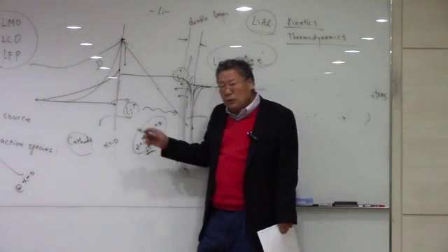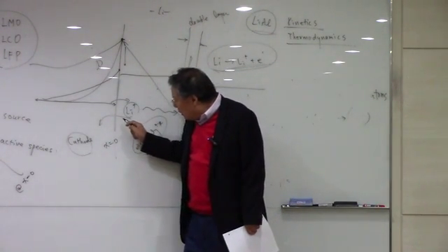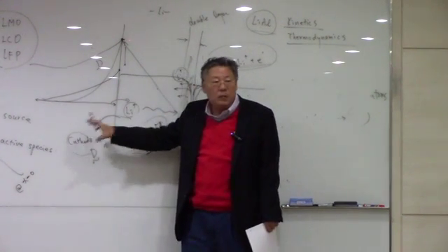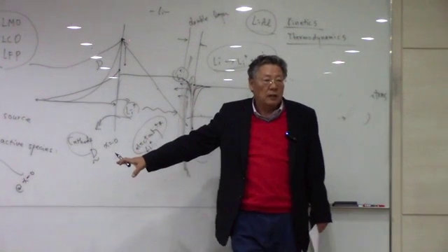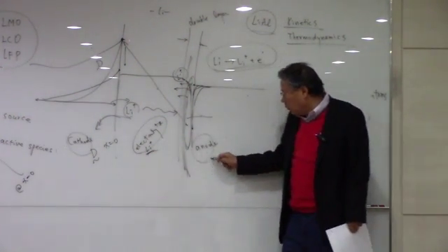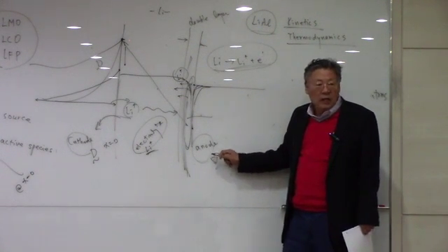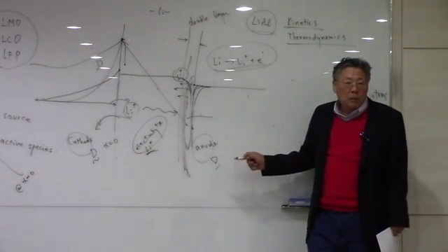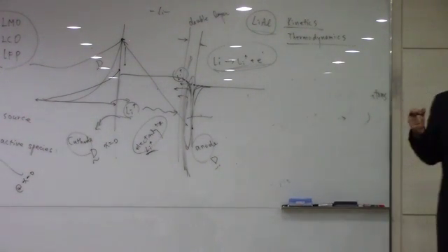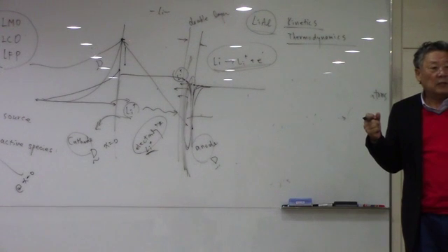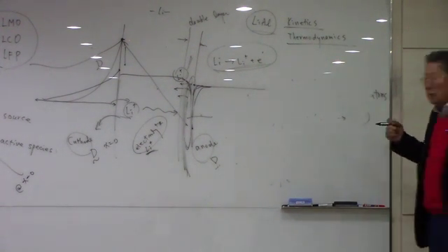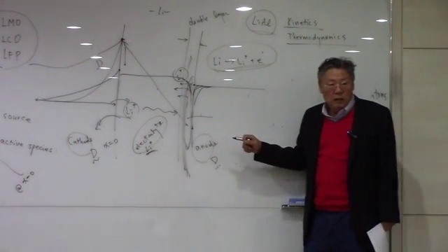As I told you, the diffusion coefficient of electroactive species in the cathode is very important and is a determining factor of this battery system. What about the diffusion coefficient of lithium in the anode? Will it be a determining factor of the battery system? It's not going to be.